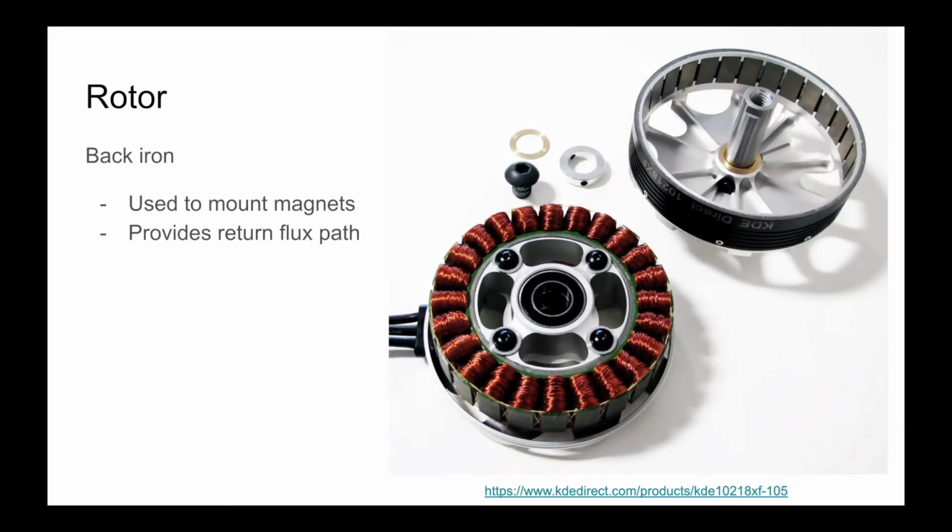The rotor is similar, but far simpler than the stator. Because there are no coils on the back iron, there's not as difficult of a trade-off. Here we just optimize our flux path reluctance while still being cautious of things like size and mass.